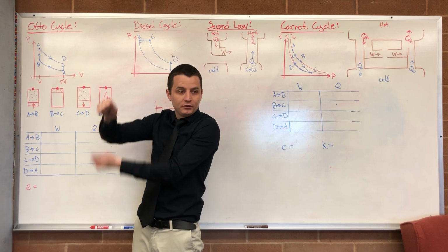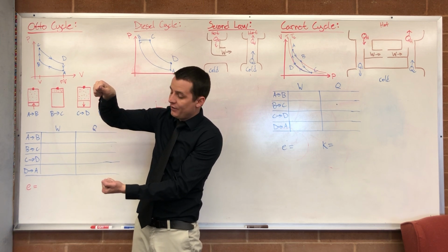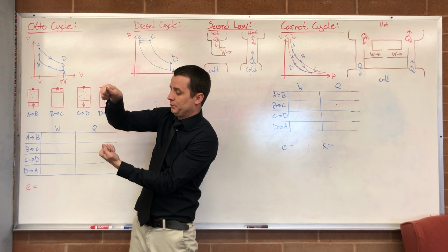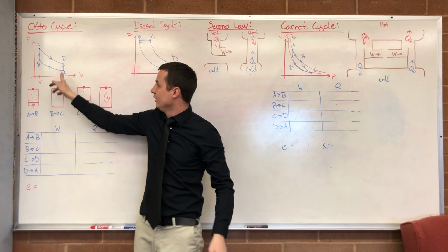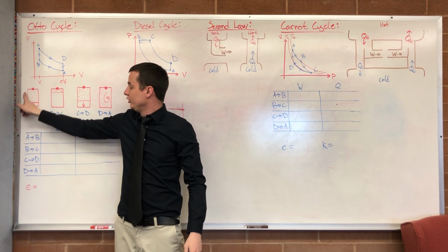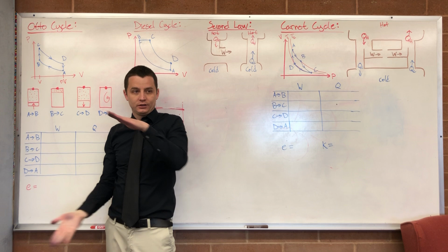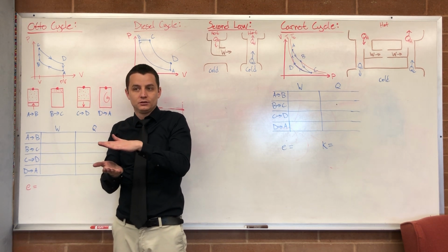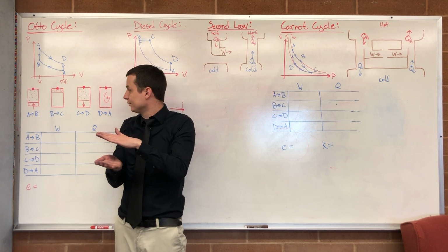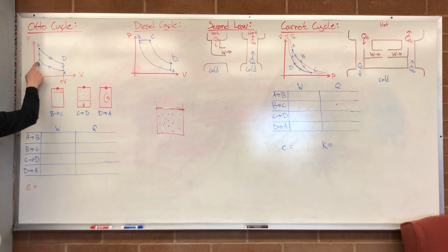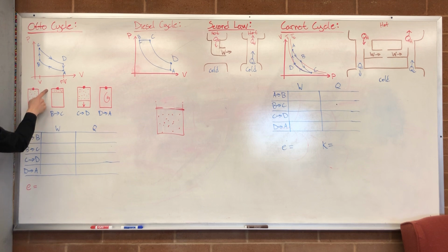Starting at point A, piston fully expanded. And then your piston, in the car case, expands and contracts from the bottom. So then your piston is going to start compressing. So from A to B, your piston started out fully expanded and now it's contracting like that. And it's going to compress the air with the gasoline fumes until it reaches its max compression, point B. So here at point B, we have the gas completely compressed now.